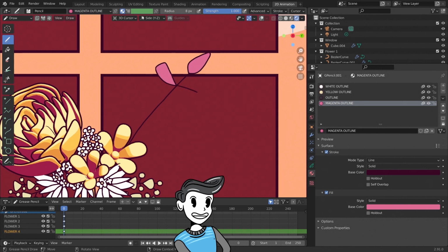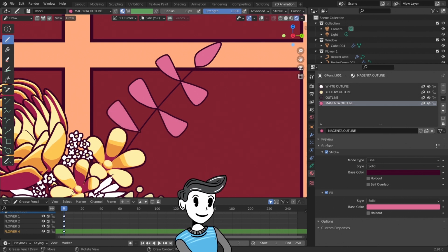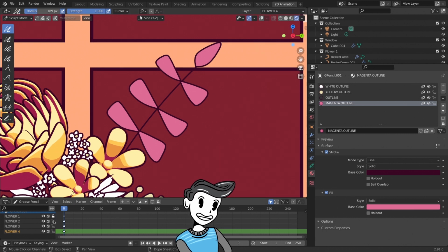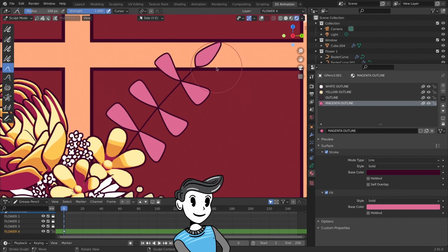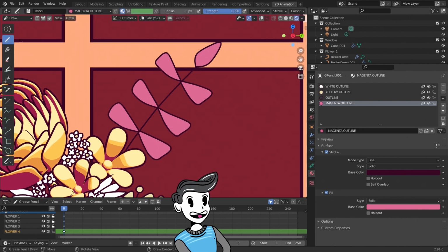I'm actually entering the x-axis view to do this, which is again technically our main view in this tutorial. So if you have wobbly lines like me, you can actually go into sculpt mode and use the smooth tool. Just make sure that your plane is still set to side and the other layers are locked when using it, so that you don't accidentally smooth those out. Now I'm using the grab tool in the sculpting options just to help with shaping. Now I'm drawing smaller petals for details.